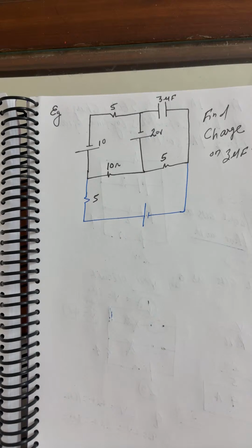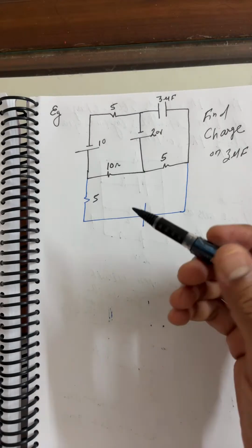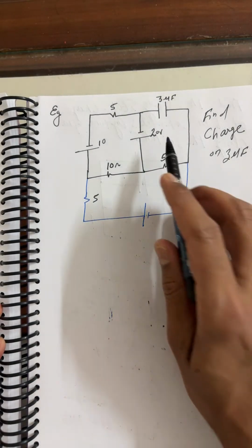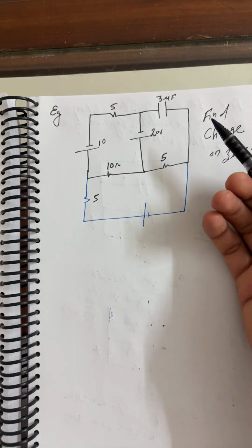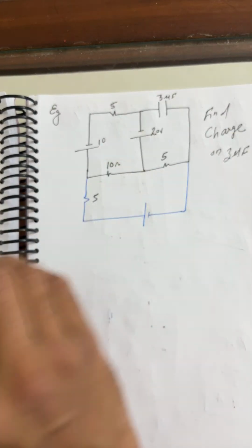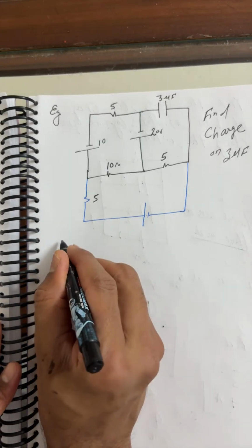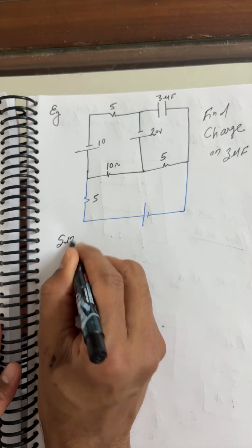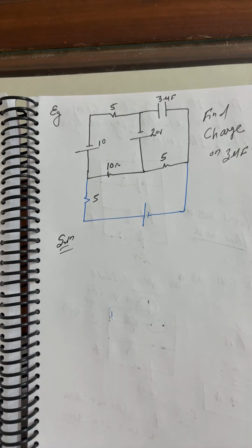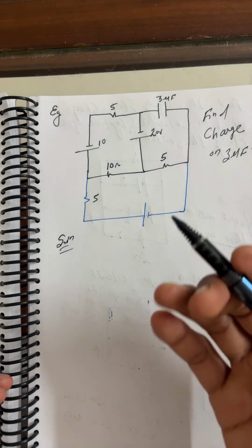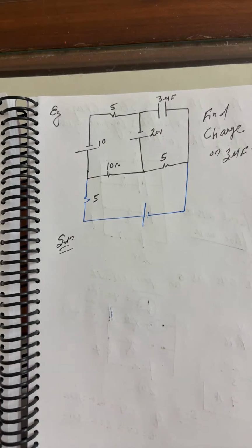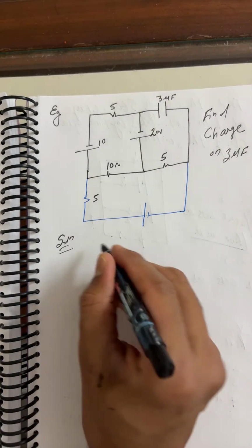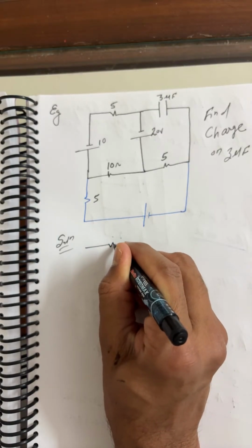Have a look, beta. How can we do this question here? Go slowly. I'll apply KVL 2 times, because this circuit as given is not useful for us. Why? Because initially we'll take into consideration T equals 0. I hope all of you remember that at T equals 0 the capacitor acts as an open circuit. So I'll again make the circuit a little fast.